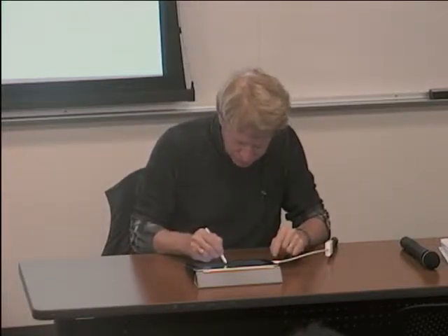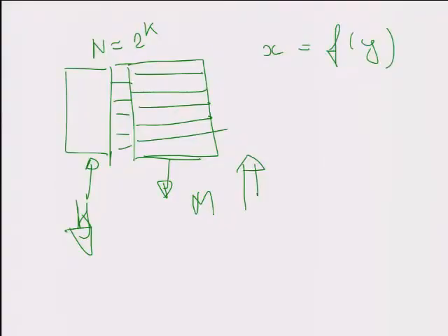With associative memory, you apply the data here. Now it's the opposite direction, and out of this comes the address on the other side. So it's kind of reversing everything. Still, we don't do any writing. The data is all basically reading. So that's nice. But what it requires is that you apply the data